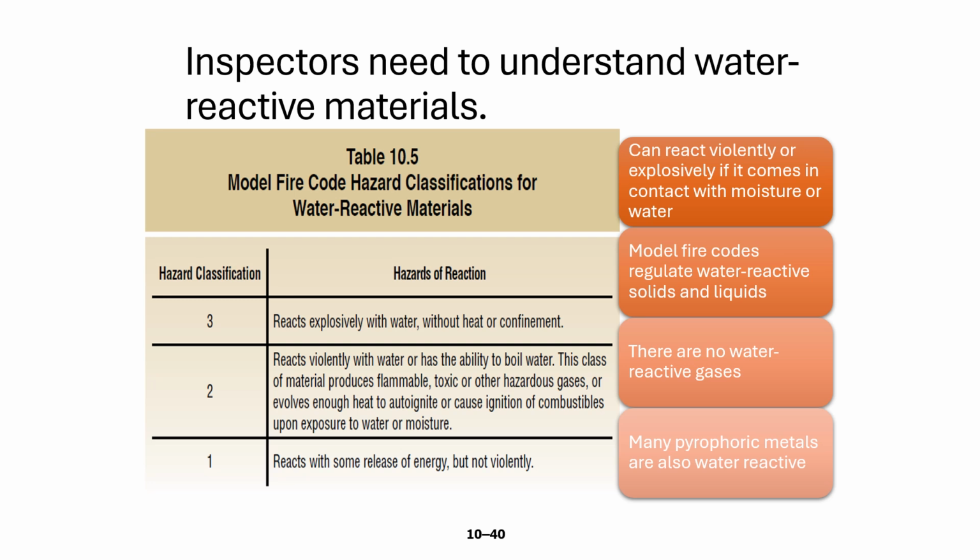These are common water reactive materials, and we look at page 395, table 10.5, titled Model Fire Code Hazard Classification for Water Reactive Materials. There are 3 hazard classifications, 3 being the most reactive, reacts explosively with water without heat or confinement, all the way down to 1, which has some reaction, but it's not violent.